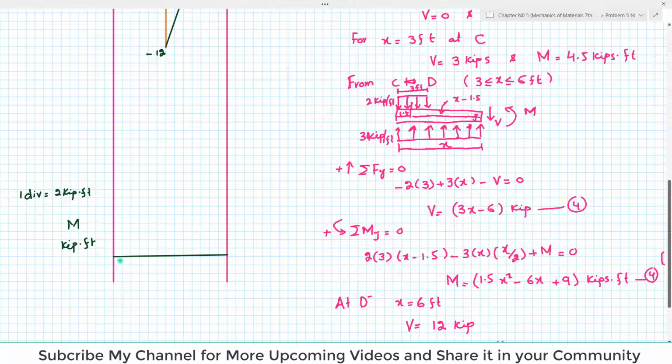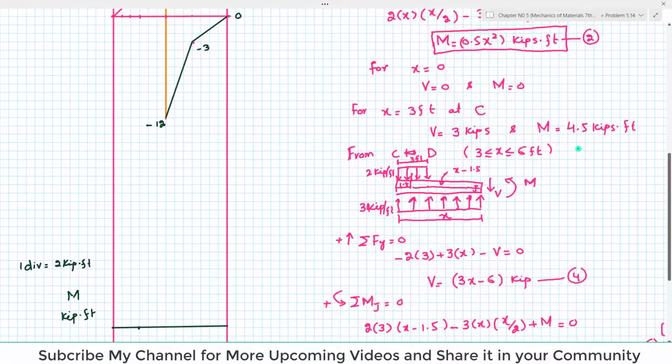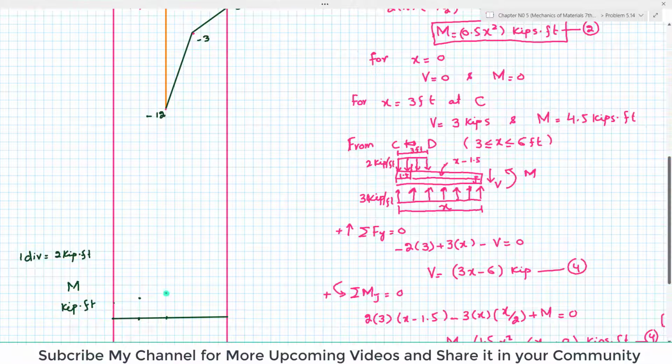So definitely at x is equal to 0, moment will be equal to 0, and at x is equal to 3 we have moment is equal to 4.5. So 1, it will be 2, 2.5, it will be somewhere here. At x is equal to 6, at the mid we have moment is equal to 27. So I will go 12 divisions above, which will be 24. 1, 2, 3, 4, 5, 6, 7, 8, 9, 10, 11, 12, 24, 26, 27 will be somewhere here. So this is 27 kips into feet.